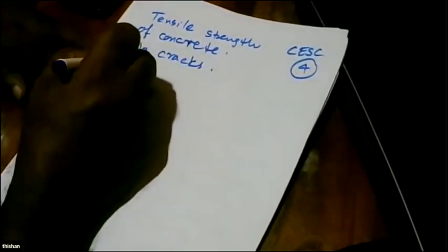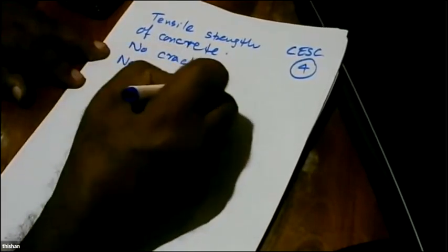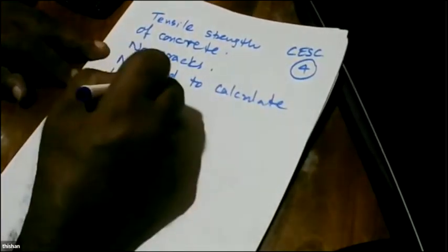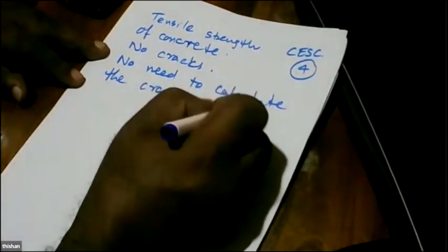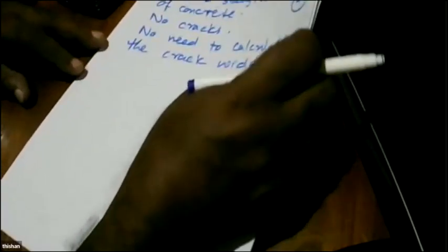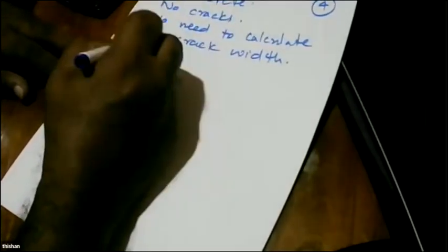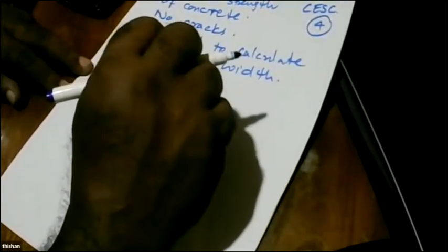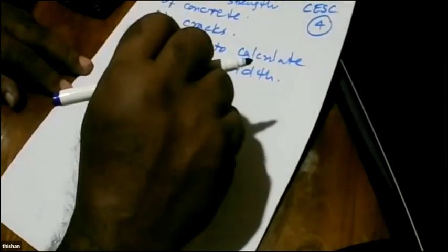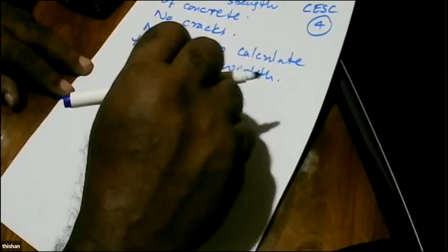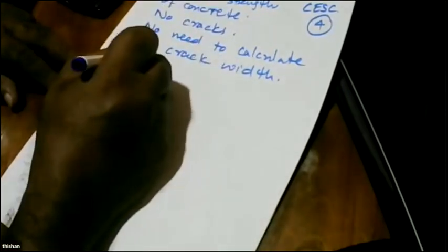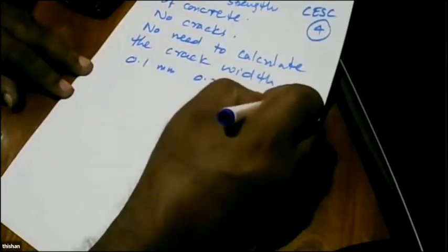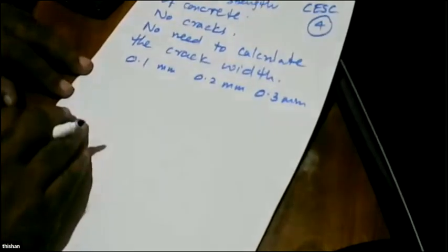So no need to calculate the crack. But on the other hand, you can stretch it a little more, and you can allow some tension and allow it to crack, and you can even go for a situation where you limit the crack width to 0.1 millimeters or 0.2 millimeters or 0.3 millimeters, depending on the type of environment.